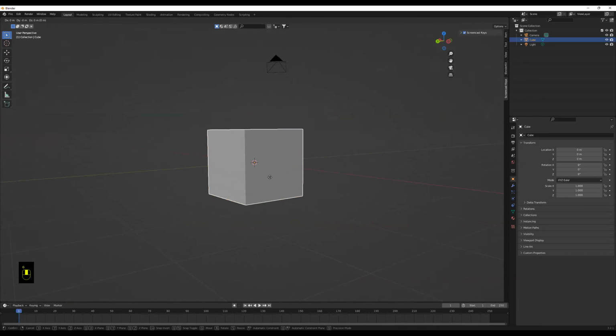Once you have that, let me move your view so that you can see the bottom of your object. And we're going to start using edit mode. First click off of the object so you don't have anything selected, and then go up to the top where we were just using select modes and use the face selector so that you can select different faces on your object.